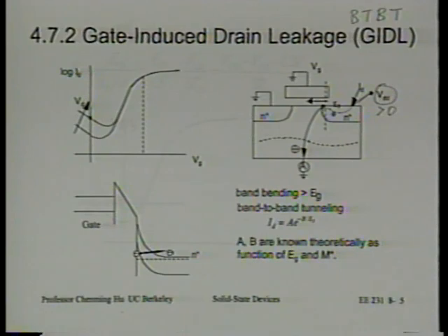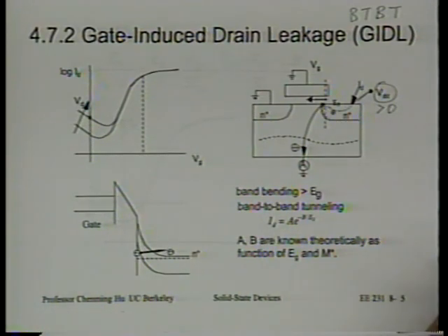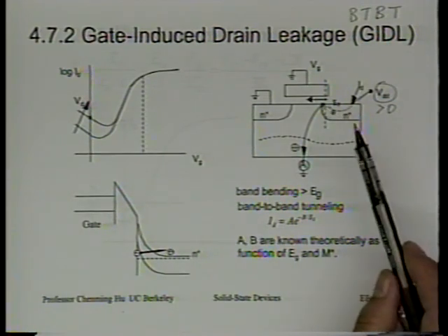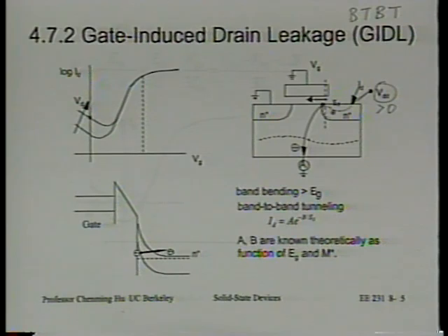It's just that we will not be limited. Band bending will not be limited at 2ΦB, that's all. It can easily go beyond 2ΦB. You remember why, right? It's because of the presence of a reverse-biased PN junction, because it's a body bias. We now get 2 Fermi levels. And the one Fermi level that determines the electron concentration, hole concentration in this case, to determine the presence of the inversion layer will require the band bending to be much larger than 2ΦB.